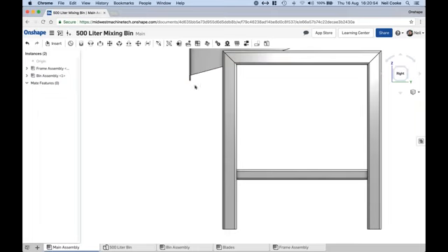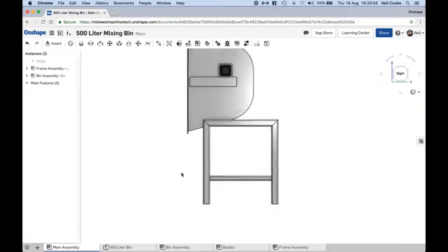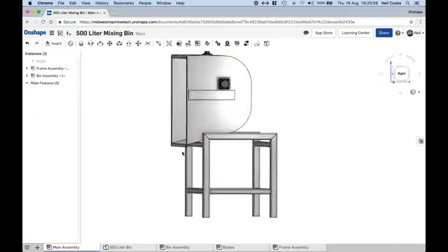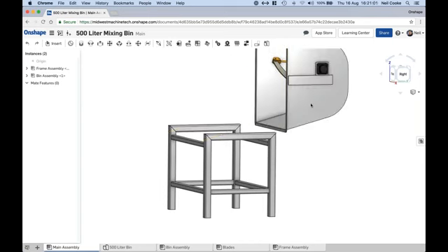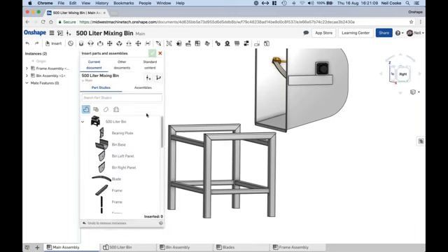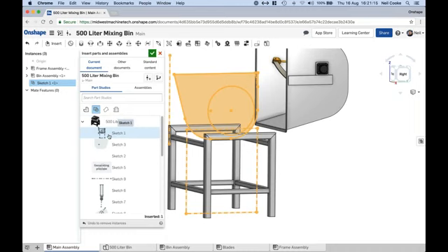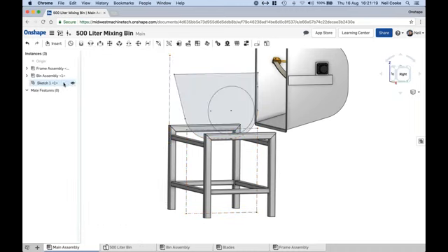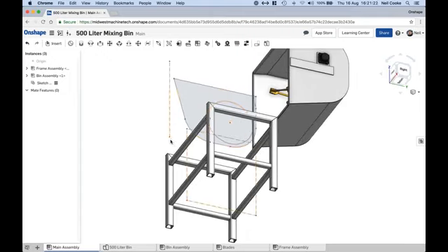So that's going to be exactly 750 from the floor. Another way you can do that, and probably an easier way than what I've just shown you there, is clearly, you can move this guy over here, and if you have the position created in a sketch, you can reuse that sketch. So I'm going to insert a sketch that was part of the original layout, which is this one here, which actually has the location, the final location in it. So the end of this point here.